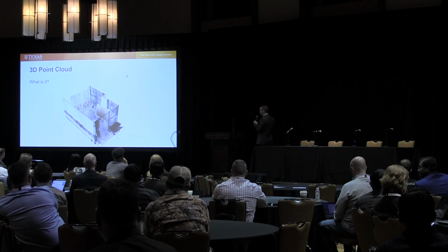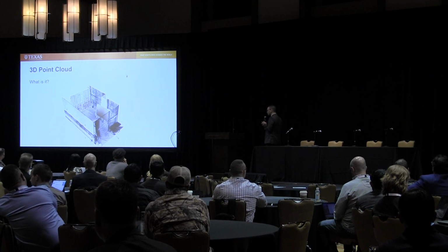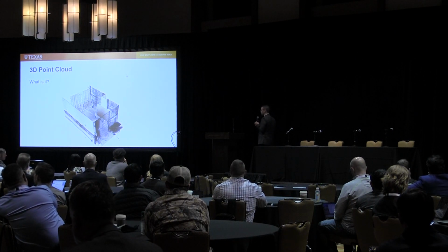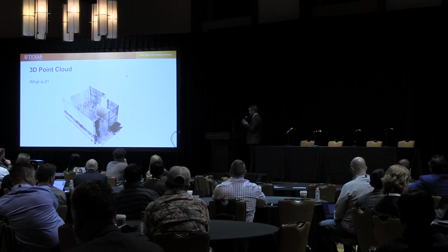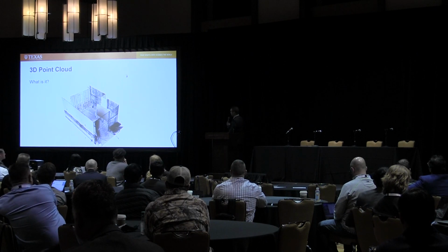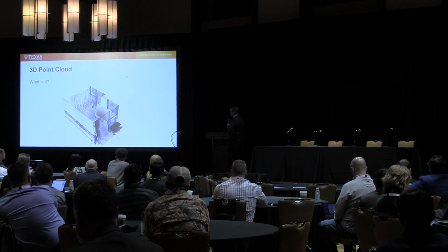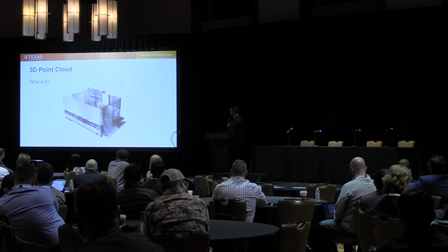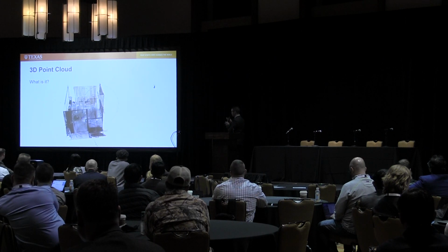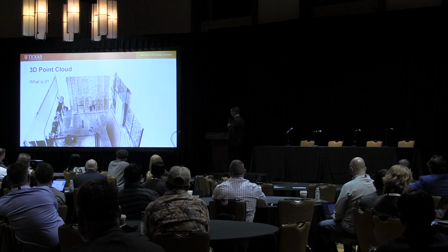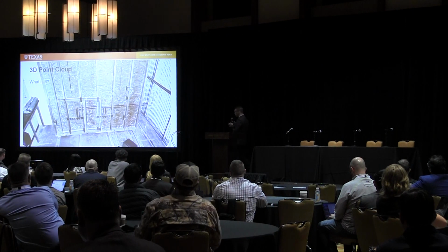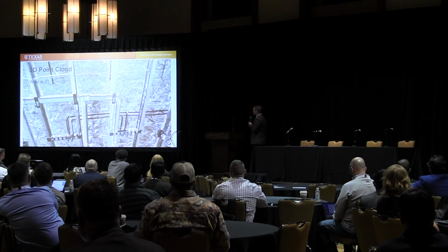So just to help give us an overview, the data that you get from laser scanning is basically a three-dimensional point cloud. That's where the X, Y, and Z come in from that acronym as well. And what we're looking at here is actually a simple scan that was taken of my lab, just a few blocks north of here. And if I zoom in, you can see the quality and resolution of this data capture. So this was 4 scans, took me about 15 minutes to capture.